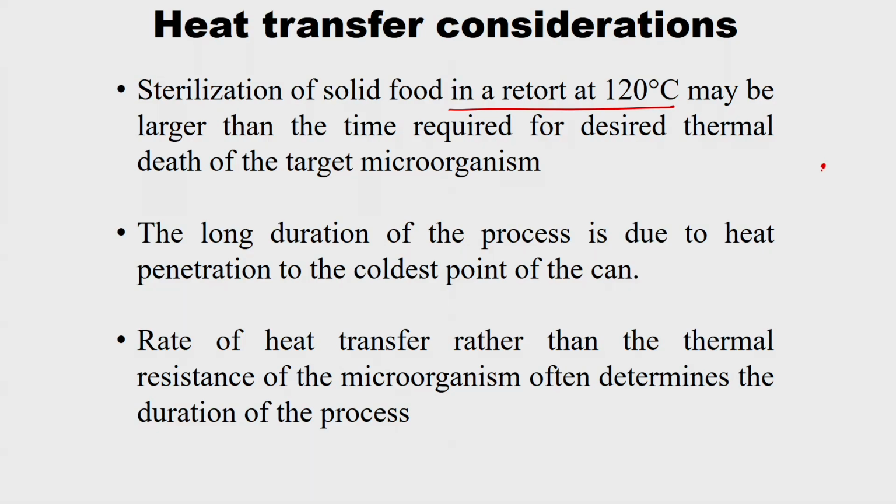So normally what happens is, we already discussed about, right. So the temperature of the coldest point of the food should reach 120, so that my target of thermal processing would be complete, right. So more than the thermal death of the target organism, the time required is chosen based on the heat transfer considerations of the food product. For example, if it is a solid food with less thermal conductivity, it will take longer time for the temperature to reach the coldest point, right.